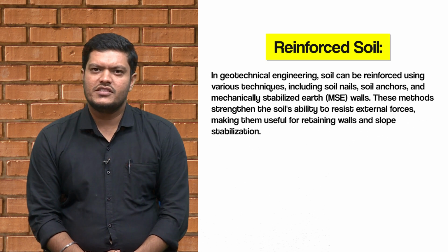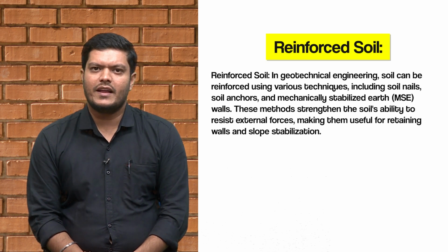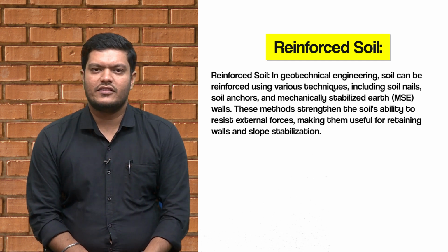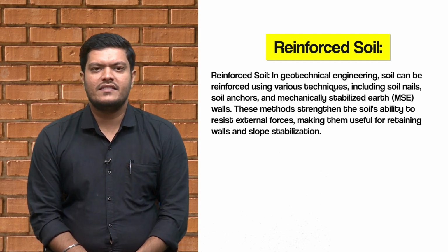Reinforced soil. In geotechnical engineering, soil can be reinforced using various techniques including soil nails, soil anchors, and mechanically stabilized earth (MSE) walls. These methods strengthen the soil's ability to resist external forces, making them useful for retaining walls and slope stabilization. In some cases, retaining walls may require reinforcement with geogrid or other materials to enhance